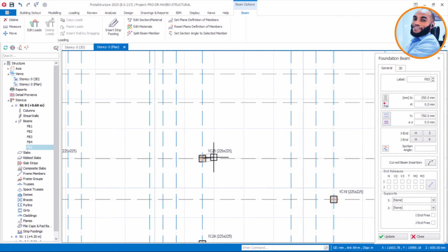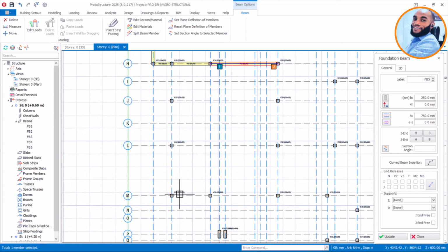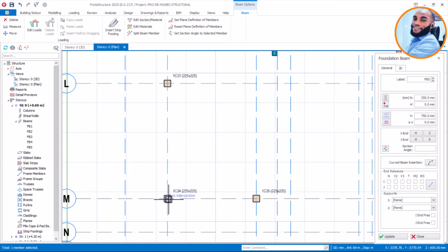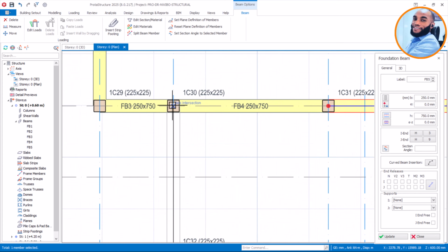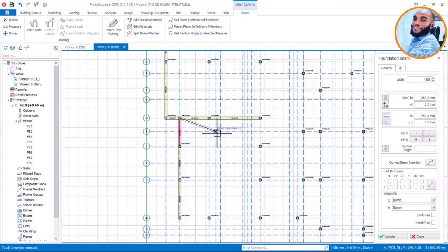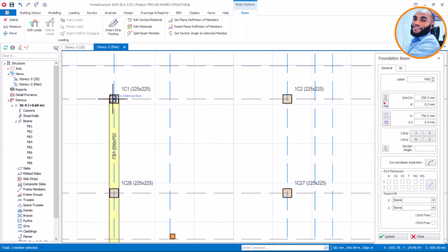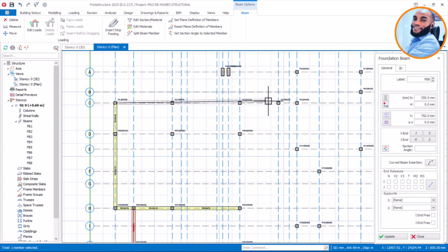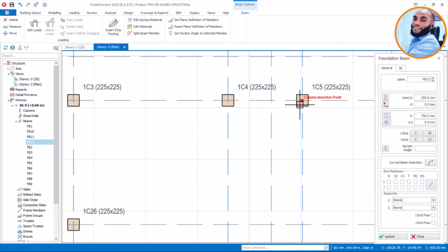Now, when you're following your beams, try to follow your wide strip foundation beams where the major walls are going to rest on, which is the major walls of the ground floor. Target your beam placement for your wide strip along that line. So in this case, I'll focus on the particular line where the major block walls on the ground floor are going to pass through.